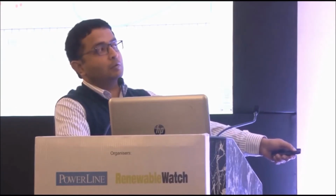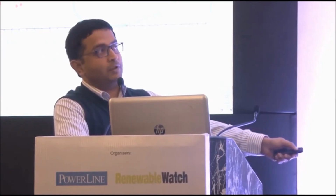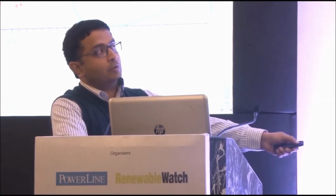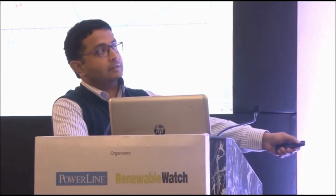And when there was cloud movement, this blue thing shows up when there is cloud over the solar array, and there is no cloud cover over the pyranometer. So the pyranometer is measuring high irradiance, but the solar array is actually not seeing that. Therefore, it is recording lower power. And on the other hand, in this case, there was cloud cover over the pyranometer, so it is recording less irradiance, but the solar array is not seeing the cloud cover, so it's actually generating more power, right? So both of these kinds of points will affect the PR at the inverter level, but they don't point towards any kind of quality or reliability issue in a plant. Okay, these are just false flags.